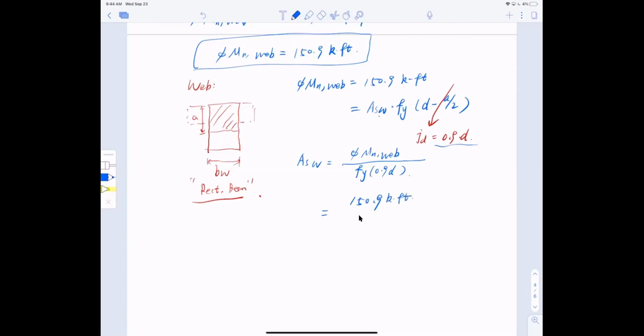Hey, Bob, I have a question. Go ahead. Do we need to take the phi out? Because isn't the equation just for Mn rather than phi Mn? Yeah, wait, hold on just a second. So I do have to take the phi out, I think. Right here, this is phi, and then this is 0.9. I just realized that. So cancel that. So phi should be here, and then this should be divided by 0.9. Make sense now? Yes, thank you. Yeah, sure, thanks.